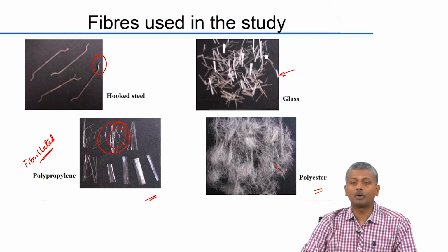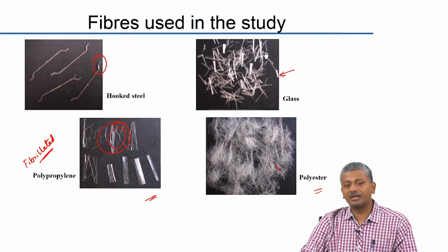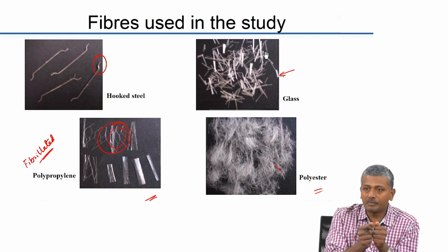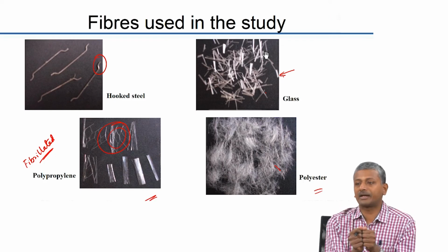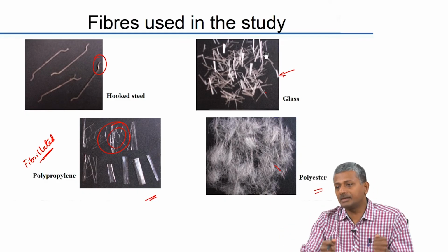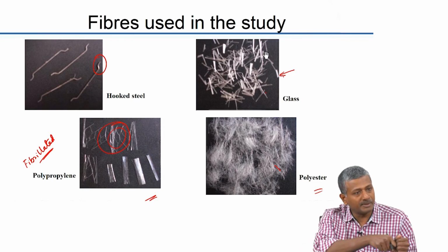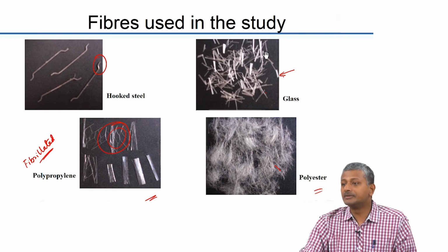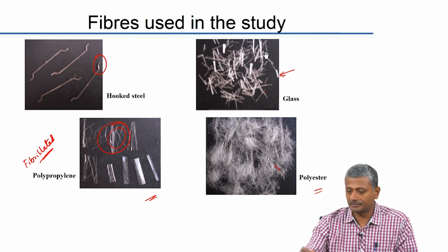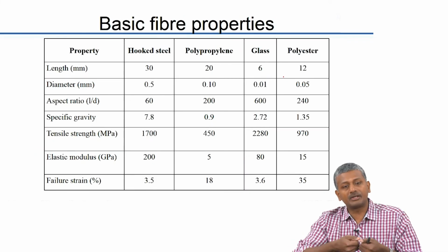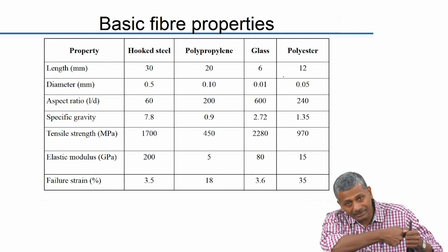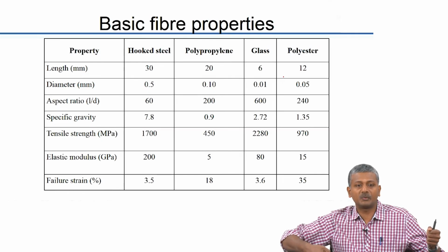But with steel or with polypropylene, the system does not fail very fast because the fibers themselves will have a large capacity for deformation. So, fibers can deform a lot, and then if you really want to maximize the use of the fiber, you want it to have a failure with which it gets pulled out of the system rather than gets fractured. You want the fiber to completely pull out of the system, and that should lead to a failure. That means that you will absorb a lot more energy before failure actually happens, and that system will exhibit greater toughness. But then imagine that to really cause that pull out, first you are overcoming the deformation capability of your fiber, and then you are utilizing the bond stress between the fiber and the concrete.